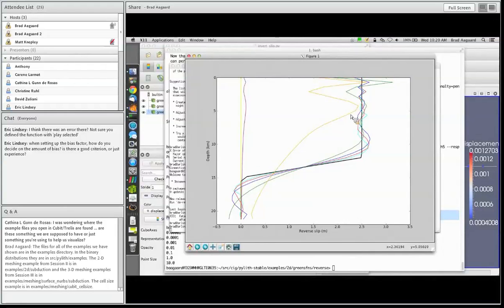So I'm relatively confident the slip distribution looks something like this, relatively uniform with depth, and then decreasing, with the decrease occurring somewhere between 12 to 17 kilometers. I don't really know about the other parameters; they have significant deviation, so I think I've over-smoothed my solution in those cases. So that's it for this 2D Greens function example.